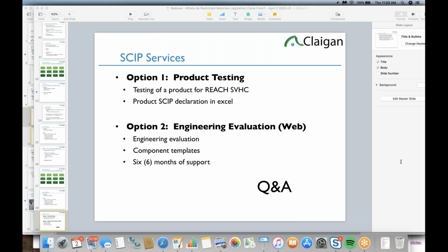PVC we'll see in a lot of different things, usually in building rules in the US for LEED, which is not very helpful because PVC can mean anything. There's flexible PVC, there's rigid PVC. Can PVC be dangerous? Absolutely. But not because of the PVC, it's because of the additives, the plasticizers and the secondary plasticizers and the flame retardants and the colorants and the stabilizers. Those are what's dangerous. PVC itself is not dangerous.